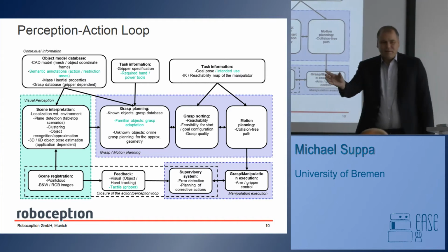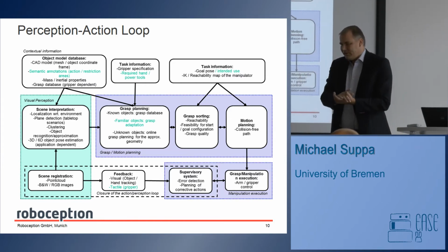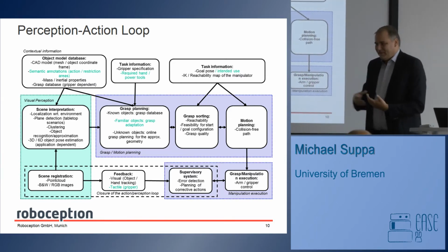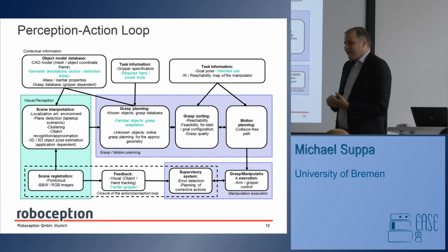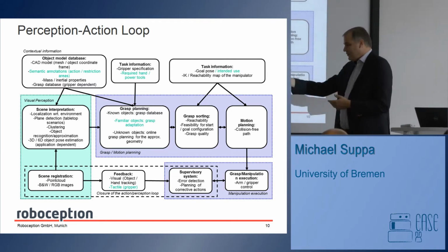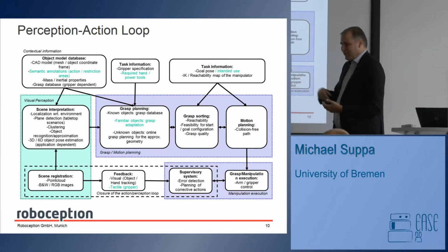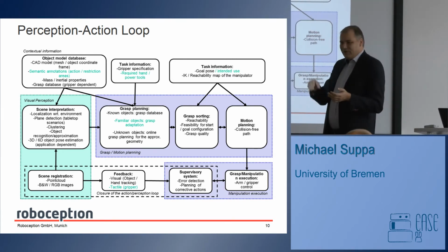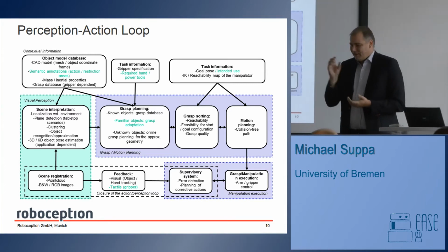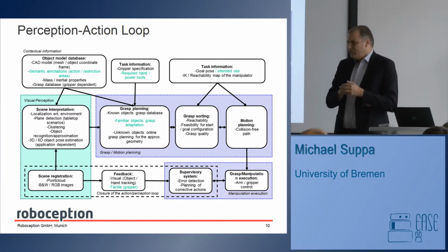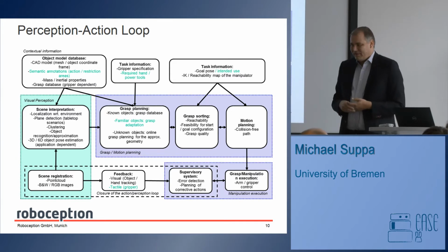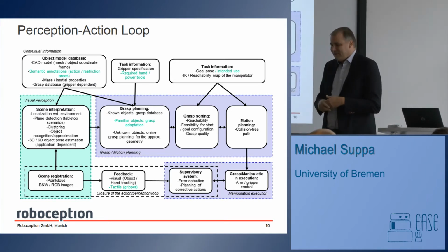So you grasp something, it shifts a little bit in your gripper, you don't grasp it in the right position, a little bit off, and then you have the task of pack and hold or exact placement. So how do you ever control that in the end? You're assuming you have the object in your gripper, it's in that orientation. So if you do just pick and drop, no one cares, right? You will always drop it somewhere, that doesn't really matter.